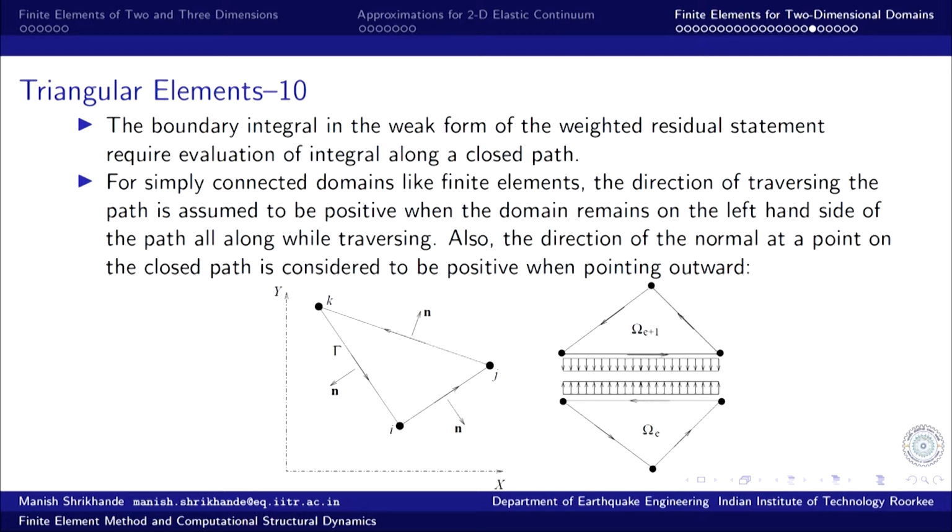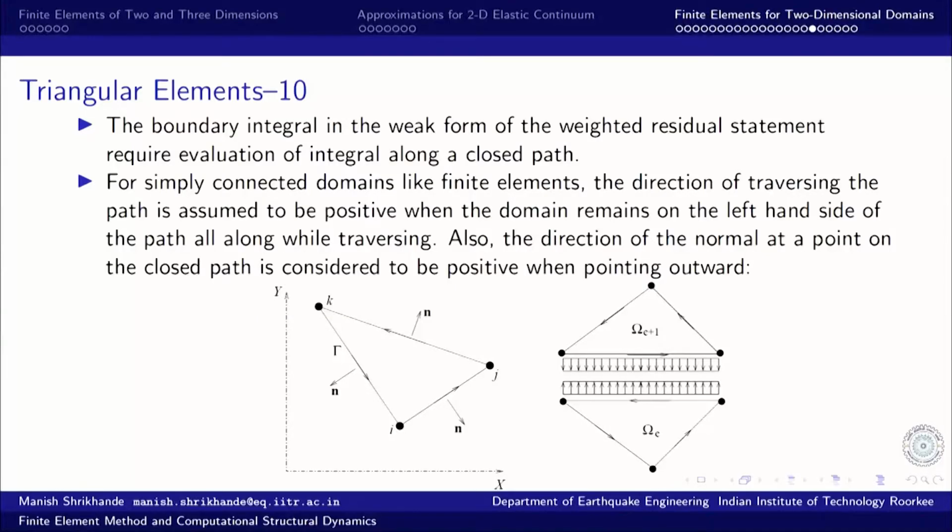This is the same thing as what we had in the case of the first one dimensional element, with the common nodes between two elements when they add together. Secondary variables tend to cancel out each other because of their opposite signs. So, secondary variables on two adjacent elements on the common boundary turn out to be of opposite signs and they would cancel out.